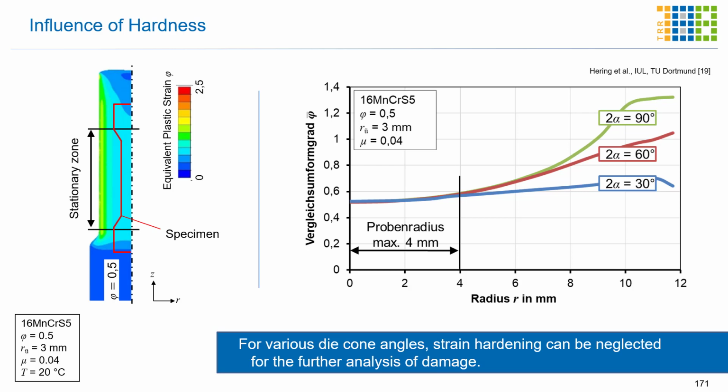Only for the outer surface the strain hardening differs, but this is not a problem since we manufacture tensile test specimens out of our extruded components to assess the fatigue life as well as the performance afterwards. So in the area of interest, within the specimen which is manufactured out of the extruded components, we can ensure that the strain hardening is the same.